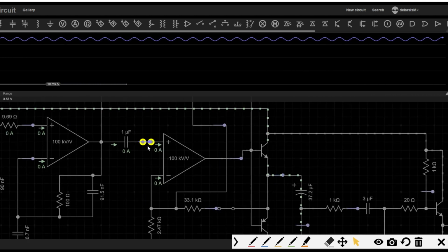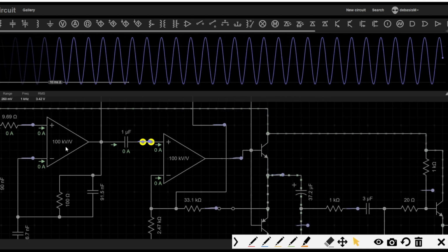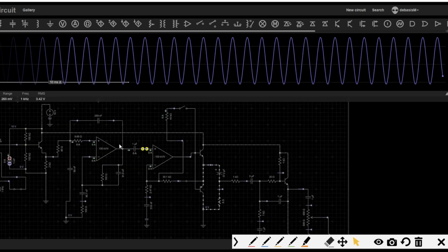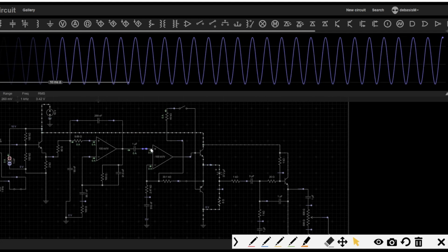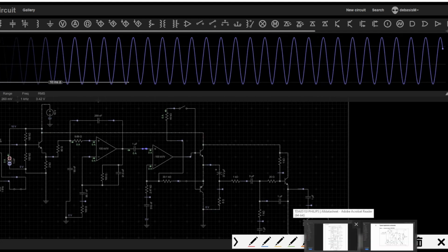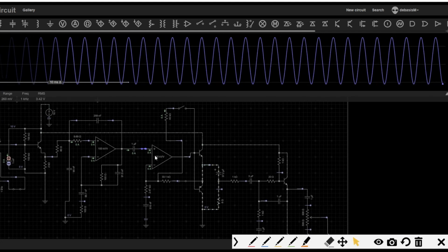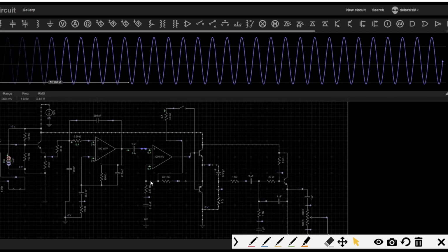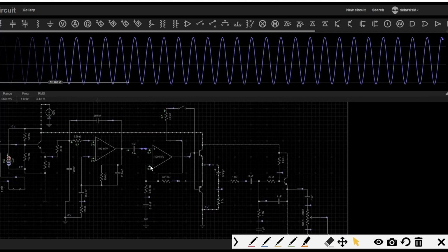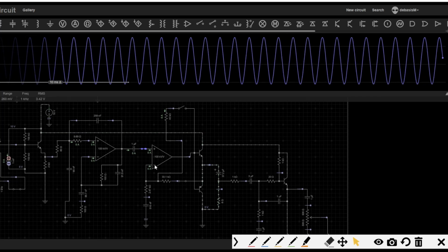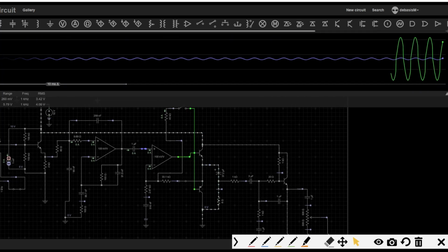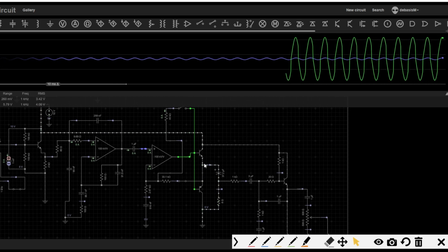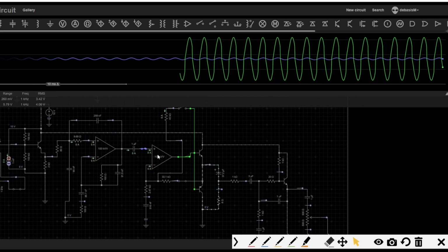Here this point is a signal from the audio filter, that low pass filter, to remove the hissing sound. This signal enters into that TDA8510J IC, one channel. When the voltage is high, meaning it is significantly different from the base or inverting point, this point also goes high. See here, that high is very high because of the nature of the op amp.